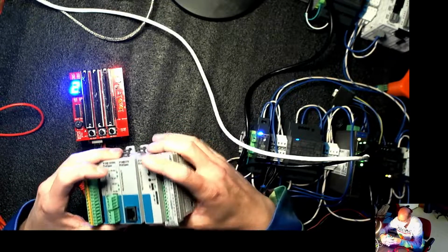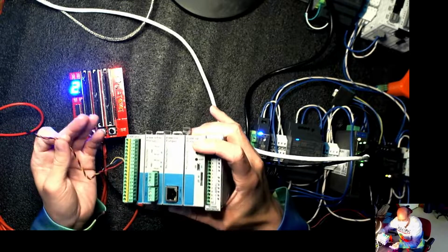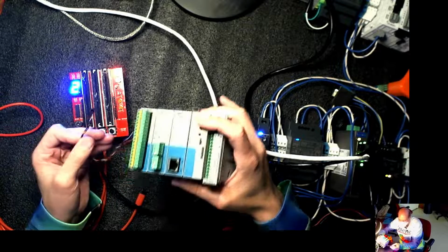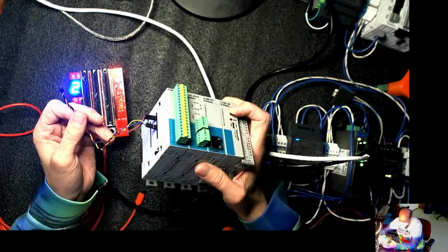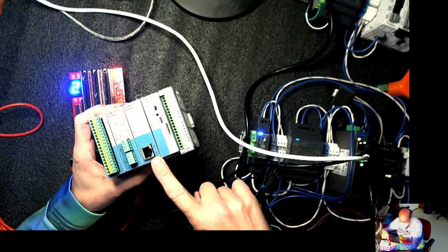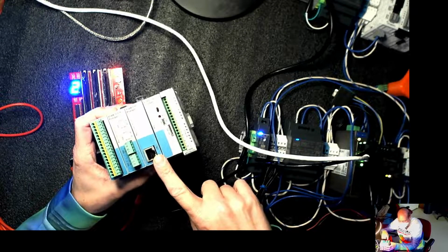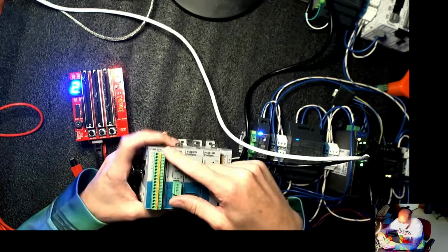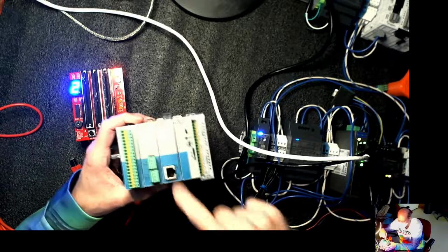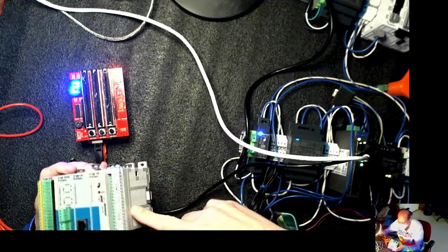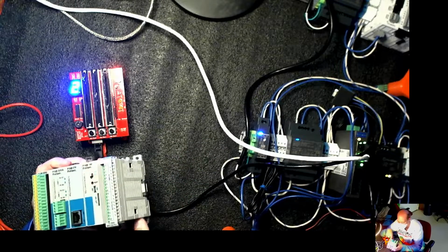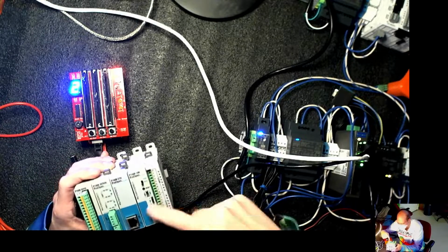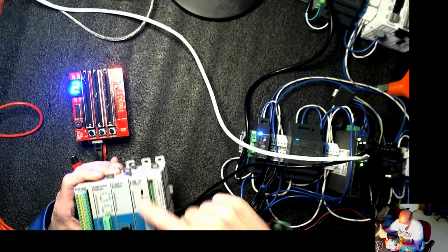So much like I was doing earlier with the quick I2C cable to the OLED and the light sensor, this will run exactly the same code plugged into the shield here. And I can also talk Ethernet TCP or Modbus TCP or Modbus RS485 with modules that plug onto it. And then this one module here just breaks out all of the remaining pins. So these pins are 3.3 volt logic because they go straight into the CPU. And then the IOs snap into the side and have their own little controller inside that talk to another controller on this board inside. Internally, it actually talks SPI from the M0 to an STM32, and then that talks down the IOs.